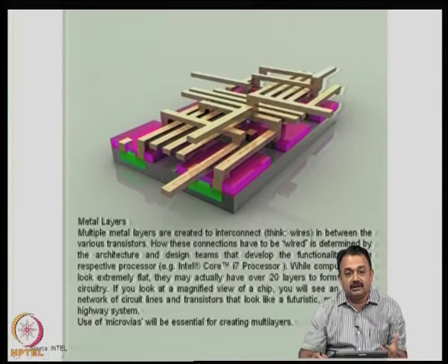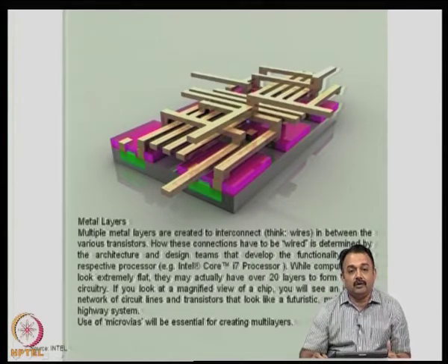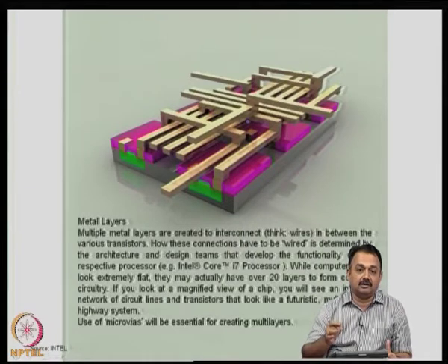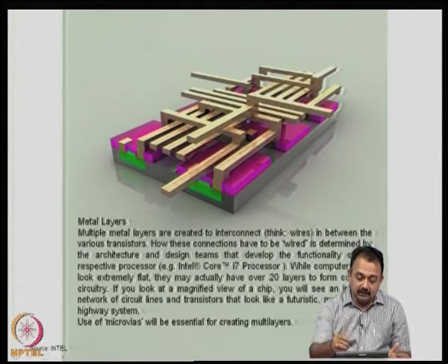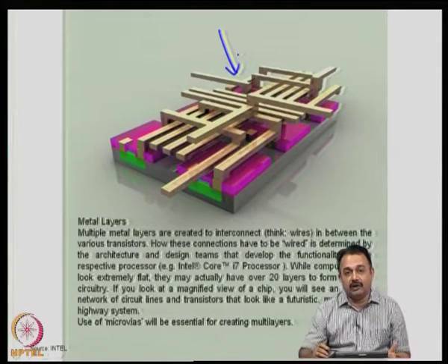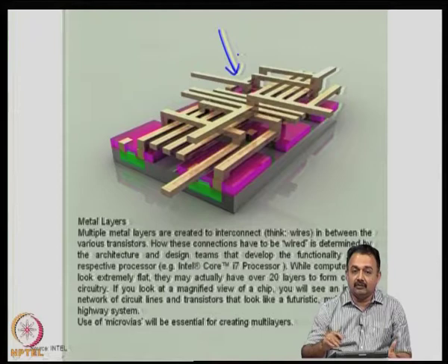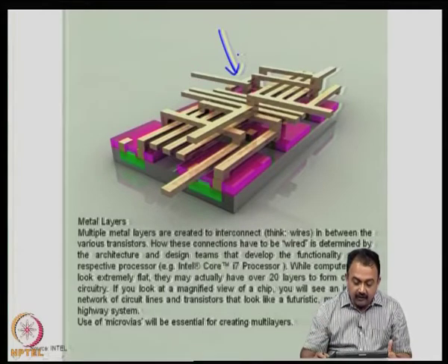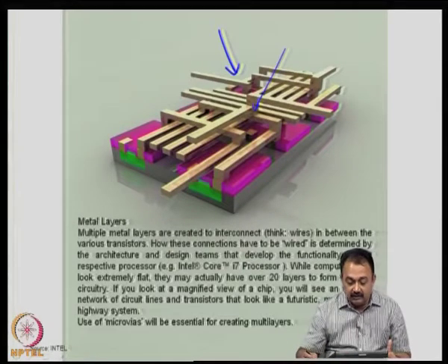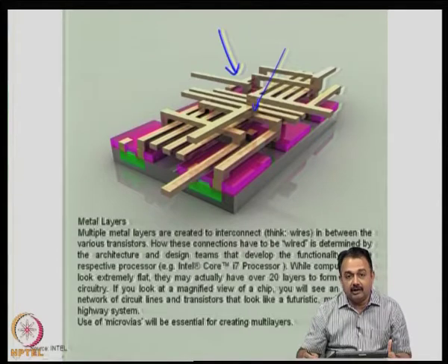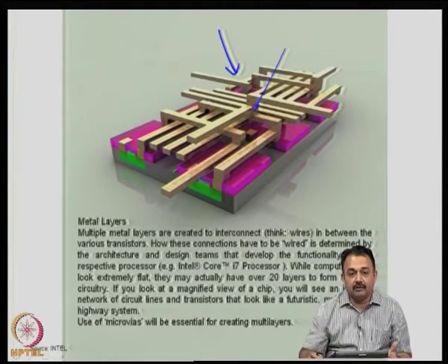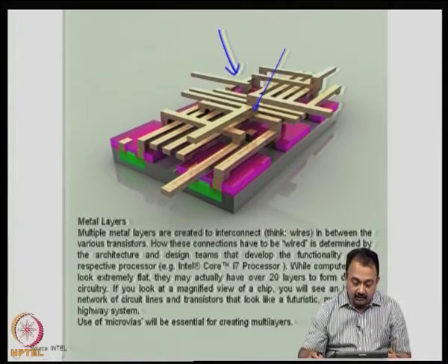Now that the basic transistors have been formed in the base layer, now we are going to interconnect between transistors using different layers. So, this picture here shows you how interconnect wires are formed to connect the various transistors below. So, this is also known as the wire. So, wiring density here is very important, and in this particular case, for example, the connections here are between various layers of copper interconnected by small vias. Micro vias are used to create connection, established connection between various conductors.